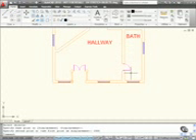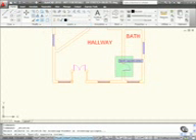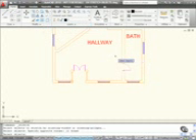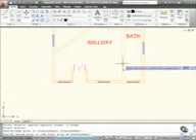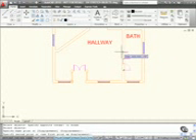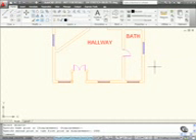Now you can move objects using the stretch command. It's real easy. If I click on stretch here and just left click there, drag upwards to the left and do a crossing selection like that, and then right click to confirm. I can just pick a point on that door now, go vertically upwards, type in 2000, and that door moves back to its original position. So you can move objects in the direction of your stretch plane as well. Notice nothing else changed there apart from the door position. All that stretched were these walls. All of the door and everything just moved in the plane of the stretch.